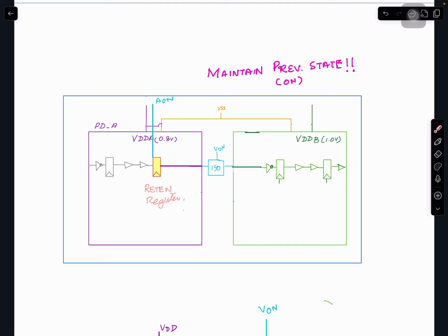Okay, that is done. What do I want to show here? Oh yeah, the third concept. You have level shifters, then isolation cells, then retention cells. Retention cells are typically registers. Let's say this power domain is off, and this circuit over here needs an input from a register in this domain. They need to know the state of it.